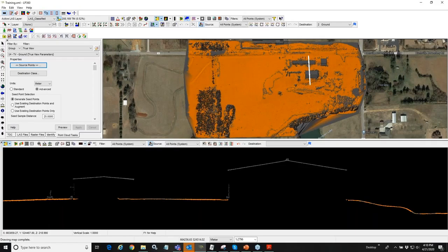Depending on the nature of the terrain you're surveying and the kind of project you're doing, you may find from doing this inspection that you do need to do some cleanup or some manual editing of the ground. That's not unusual. This adaptive TIN algorithm that I mentioned is really effective for a lot of things, but it can have areas where it has challenges. You can have some busts in the data. You may need to go in and spend a little bit of time doing some manual cleanup, some manual editing of the data. And we do have a bunch of tools in TrueView EVO that assist you with that.